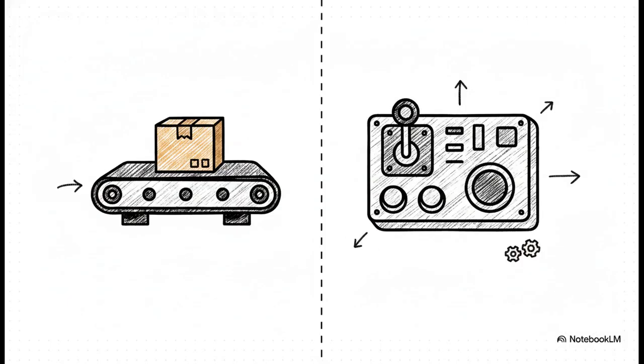Now, the absolutely crucial point is how this switchyard is organized. If you draw a mental line straight down the middle of that diagram, you reveal this incredible, elegant symmetry. Over on the right, you have the instruction path, or IR scan. On the left, you have the data path, or DR scan.